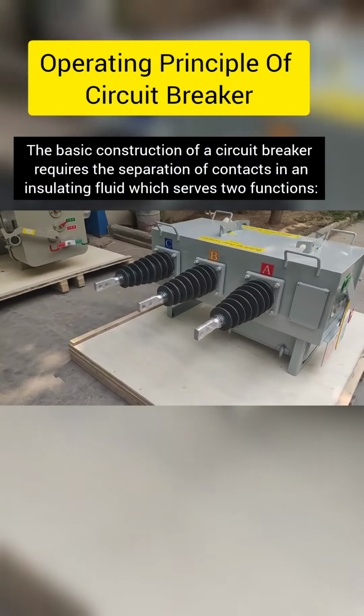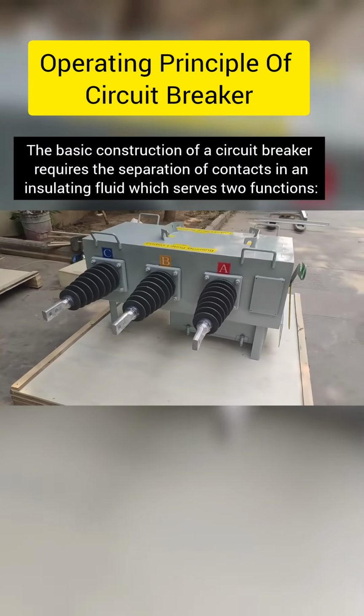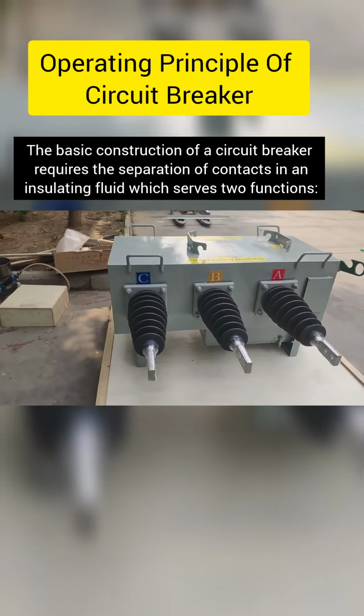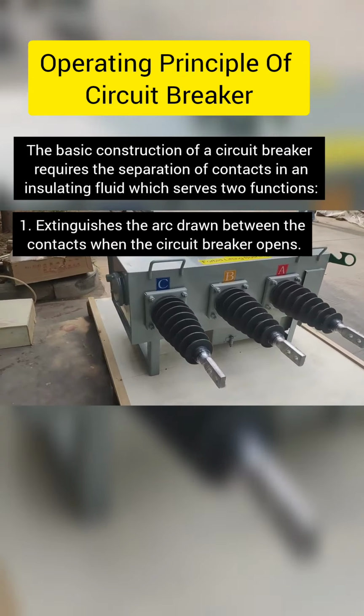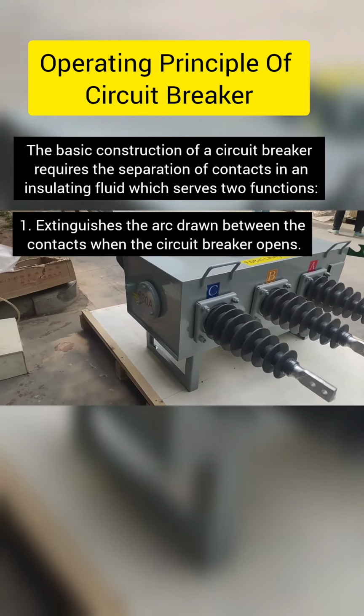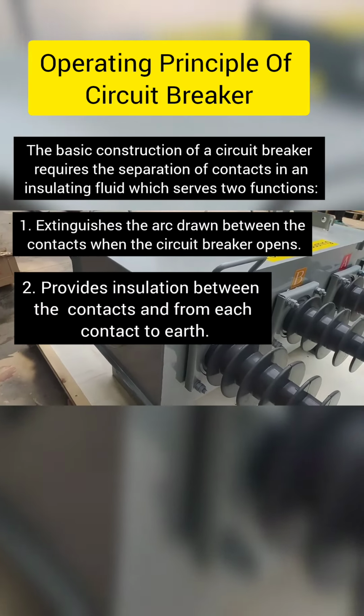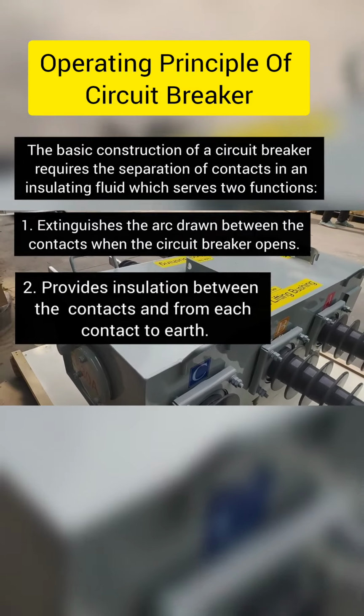The basic construction of a circuit breaker requires the separation of contacts in an insulating fluid, which serves two functions. 1. Extinguishes the arc drawn between the contacts when the circuit breaker opens. 2. Provides insulation between the contacts and from each contact to earth.